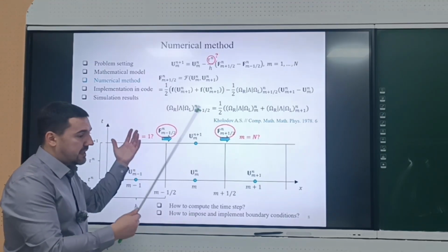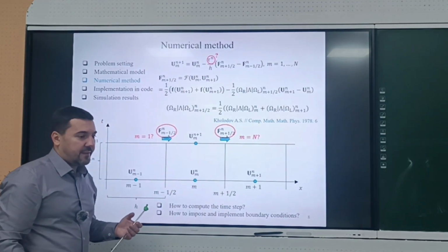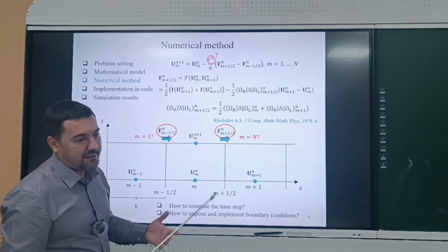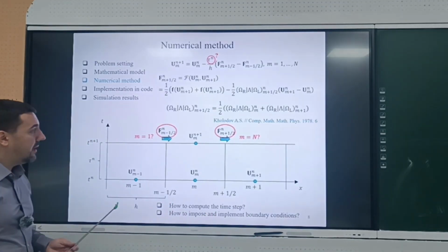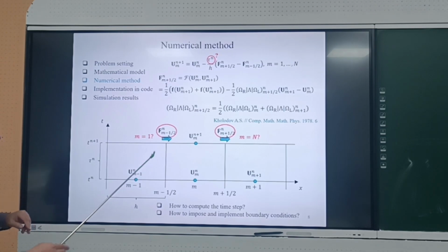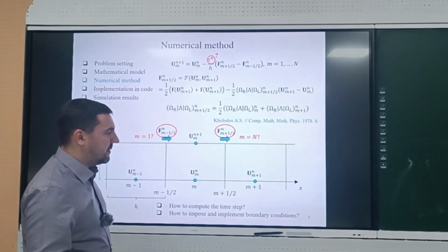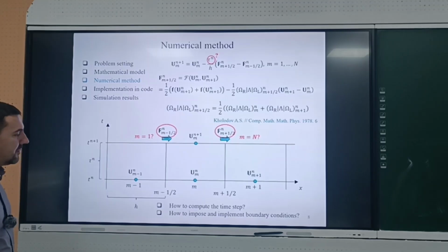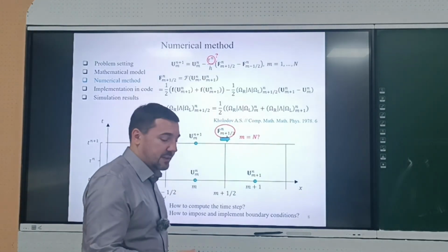It turns out that although we understand how to construct the Riemann solver, the usage of this solver in software, in code, is not a straightforward problem. You should solve some issues on how to do that. So we are going to discuss these problems: how to choose this time step tau n, and how to impose boundary conditions. These topics are of great importance; in fact, the quality of your boundary conditions and their numerical implementation totally defines your numerical result, especially in some cases.